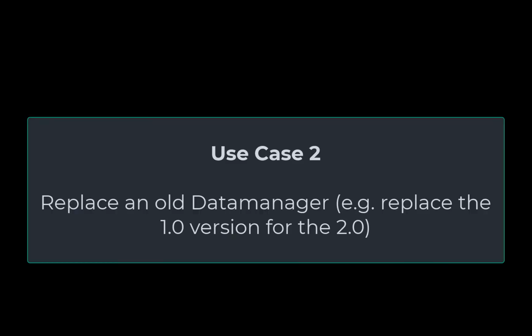Use case number two is to replace an old Data Manager 1.0 with the Data Manager 2.0, since version 2 supports the Fronius smart meter, which again is necessary for the smart metering of production, consumption, as well as making smart decisions of where to store the energy delta between current consumption and current overcapacity. If the sole intention is to produce electricity and leave all the surplus to the grid, then a Data Manager 1.0 is just fine for your production logging over the internet. Of course, same procedure if you want replacing a faulty data manager.